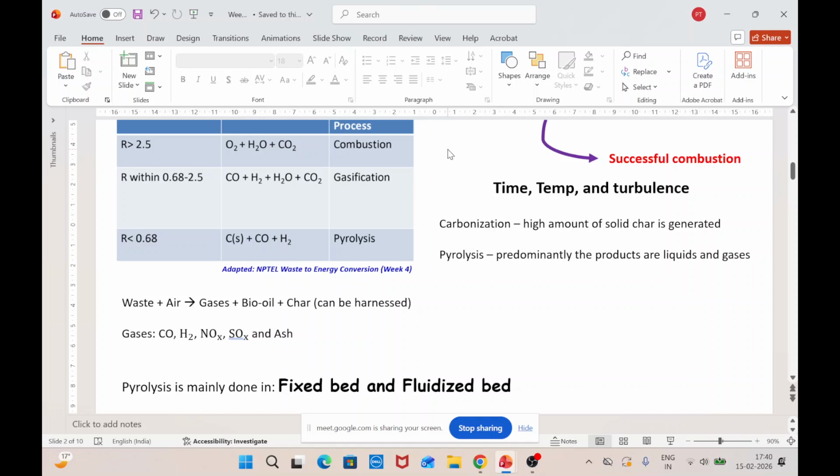there is a big list. The major principle remains the same as what we discussed for gasification, both for fixed bed and fluidized bed, and for circulating fluidized bed as well. Both fluidized and circulating fluidized beds are usually the commercial ones, and they are easy to scale up.